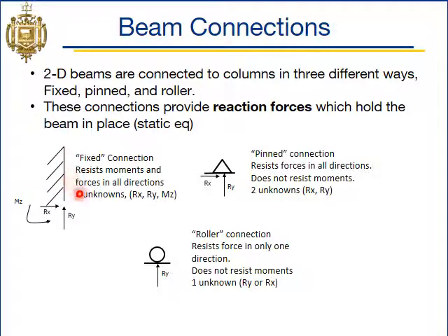So a fixed connection means that the connection is designed to resist any type of movement, right? So any type of lateral movement or rotation. You could think of maybe a heavily bolted connection or a welded connection, something where there's no ability for the beam to move from its connection.